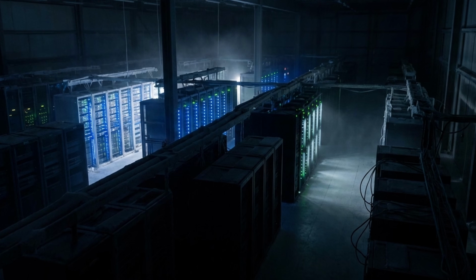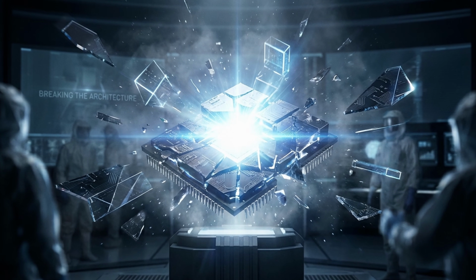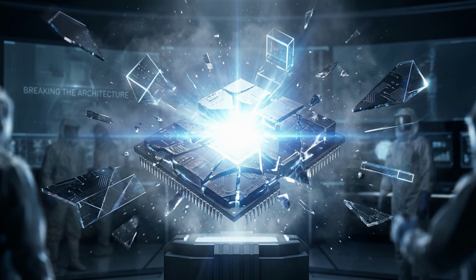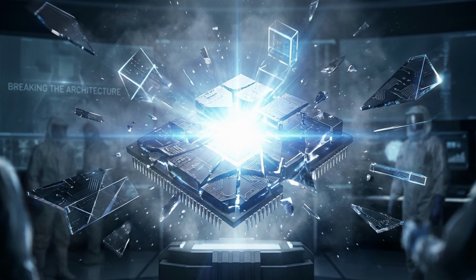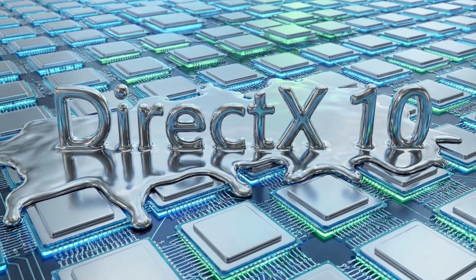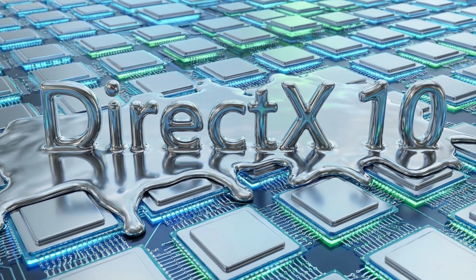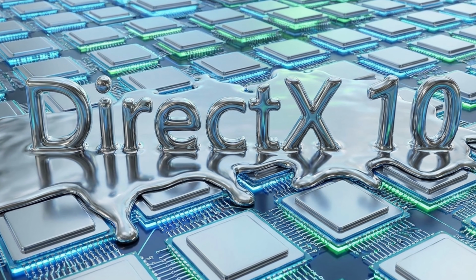was constantly being wasted. The definitive solution to this occupancy problem arrived in late 2006, marking the most profound architectural paradigm shift since the invention of hardware transform and lighting. Coinciding with the launch of the demanding DirectX 10 API, GPU designers completely discarded the concept of specialized shader units and introduced the unified shader architecture.